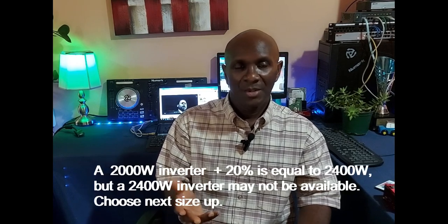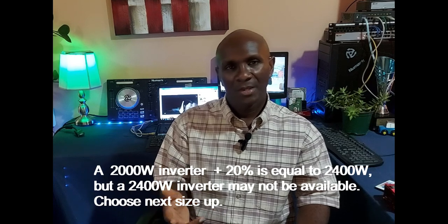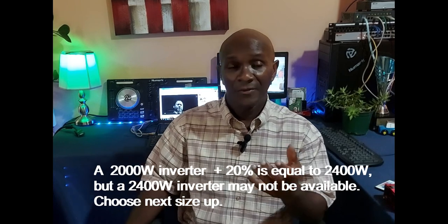Now, having calculated the total wattage need, you need to have a buffer, like a 20% buffer. So let's just say that your total consumption need comes to 2000 watts. You should not go and just buy a bare basic 2000 watt inverter. You need to add 20% to that, so you'll be looking at something like a 3000, 4000 watt inverter. The reason for that is that if you overload the inverter, you stand the chance of damaging the equipment, the appliances, the devices that you connect to the inverter, and also the inverter itself. So you can fry it. You don't want to have that happening, right? Okay, so that is how you do it.